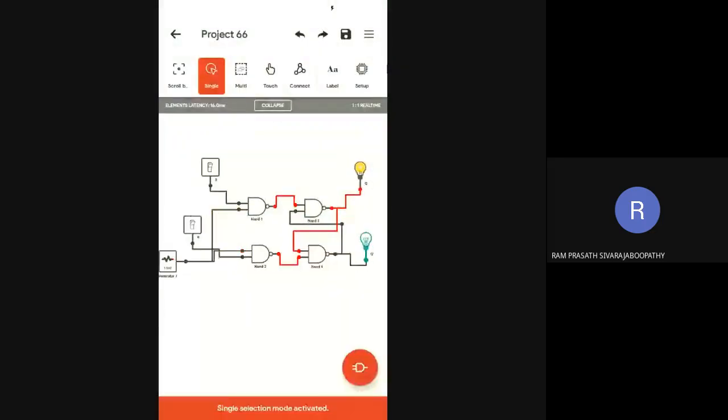So clock is permanently given. Now what I am going to do is give reset. So what about the output Q now? 0. Correct? Now the present state is 0. If I give 0, 0 as input, the output remains unchanged. Is it clear or not?